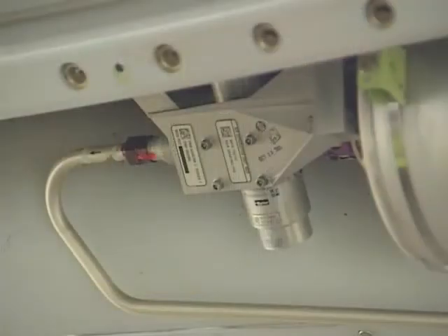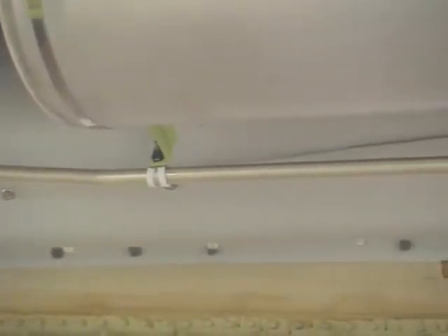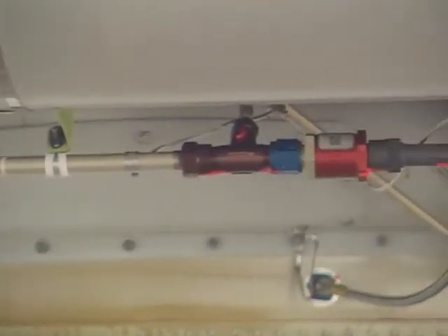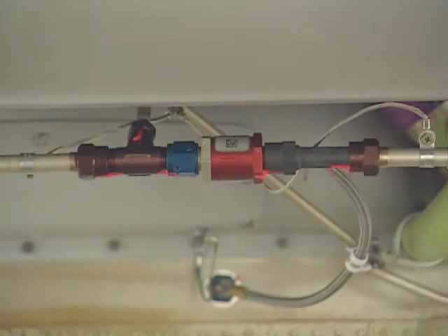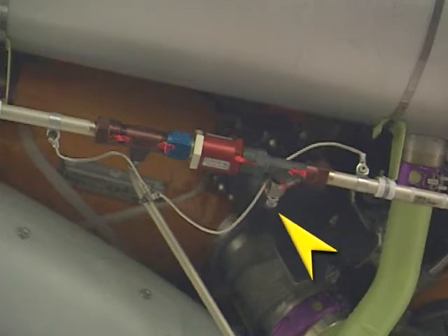From the high flow valve, the DADS line bends around and runs aft to a backflow check valve. The backflow check valve prevents fuel from flowing back into the NGS system. Looking at it from a lower angle, we can see that just ahead of the valve is a tube that goes to the GSE port. And just aft of the valve is a T-fitting with a cap for use in the leak check.